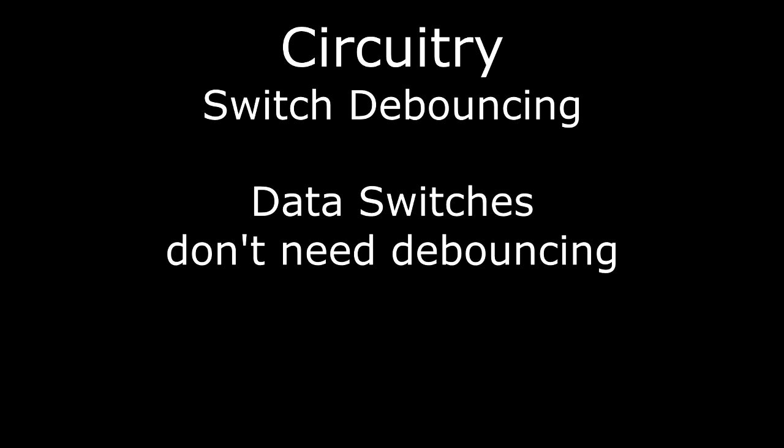If you think about it, if you're, say, toggling in a program or using it to examine memory, you set the switches, and then you'll press examine or deposit next or whatever. We're doing this in human time, and so the switches have plenty of time to settle. If you're reading them in a program at the assembly language level, you're probably slow enough that bounce doesn't matter. If you notice it there, then, hey, you can work around it in software. Not my problem. Maybe that sounds cruel, but I'm sure in reality that's not going to be an issue.